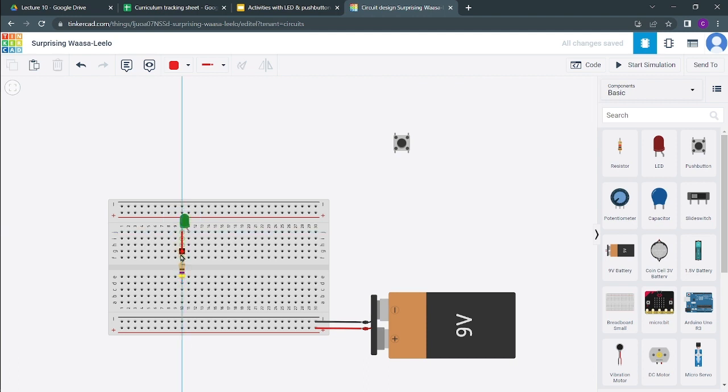So whether I connect a cable or I don't connect, it is the same. You can connect it with a cable, or you can just put it here, because each and every hole in this column is already internally connected. They are connected in this manner, not this and this, but just this column. Similarly, whatever I'm connecting here will go up to this. So I have placed this resistor here, hence they are already connected. So you don't need to use an external wire for it; you can use it and you can also not use it.